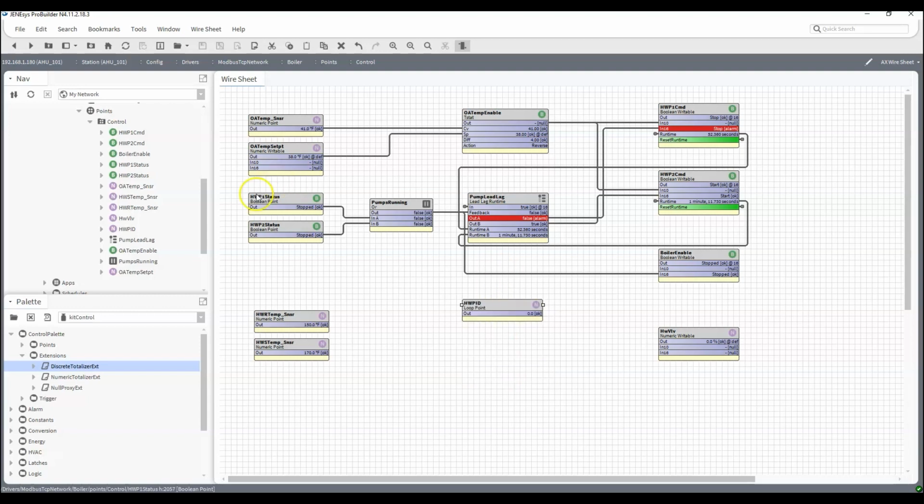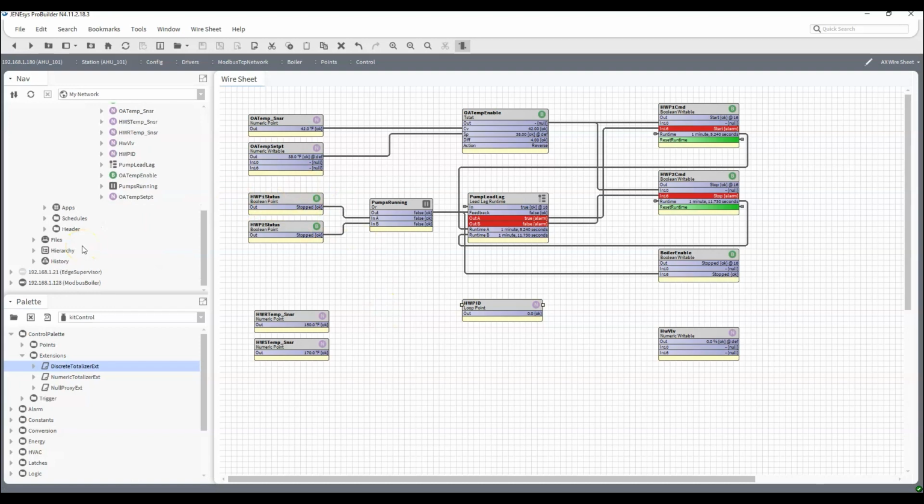So this is also good troubleshooting for testing purposes. We can see that we've attempted to start this pump, but the status says stopped. Which means that there could be a pump issue. It also could be something where the value is not being written. So we're going to go in a moment and actually check that too. Okay, so now we've got this here.